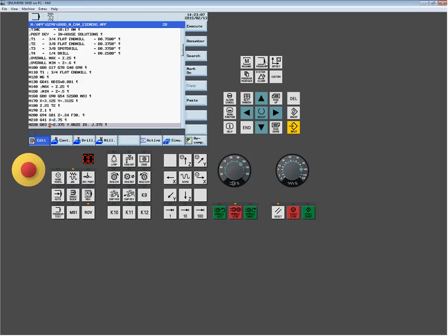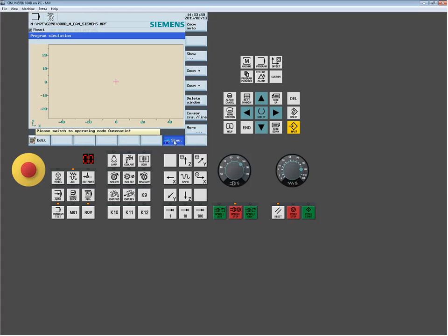So normally, TOFFL, and then I can adjust the length of an offset. So what that's doing is it's saying, okay, I understand you're telling me I've got a 3/8 tool, but in reality, I'm going to take that 3/8 away before I run the cutter path, but you still have cutter compensation. So if I simulate that same part program, I'm going to delete the window so we'll get a fresh simulation. I'm going to see the same results as I would have had before. So I'm not getting double compensation. This edge of this part would have been at 2 inch. That's correct. And now I can just add or subtract to this diameter like a real world scenario.